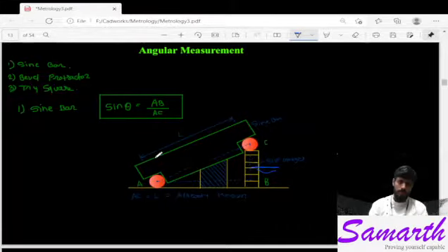As we know this length L and this height, let us say BC, you can even measure from this point to this point and up to the slip gauge, so that you get the height of the slip gauge.